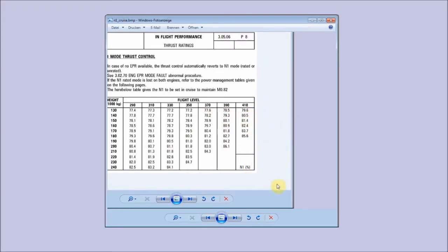And after that, I got all my basic values for the engines, for the lift, for the drag, and I could perform climb tests. So the current version of the model has, especially below flight level 100, too high climb performance. So I have to adjust that in further development steps. So now, as the basic flight model was already completed, I had to work on other things like spoiler drag, gear drag, flaps, brakes and reverser, fuel flow, and stuff like that.